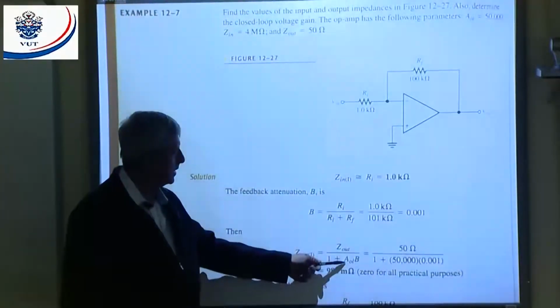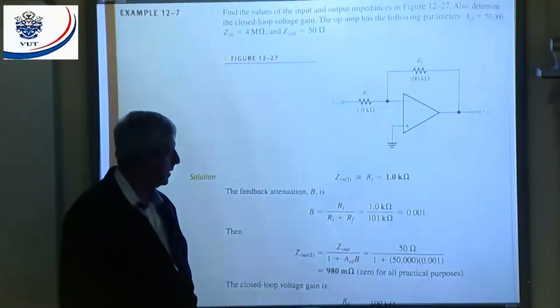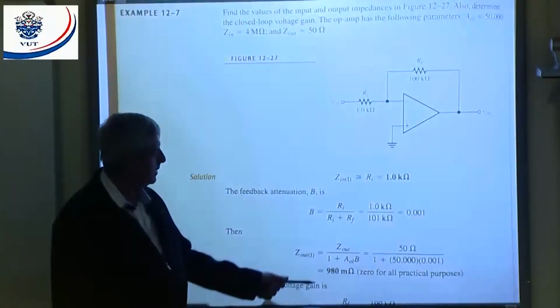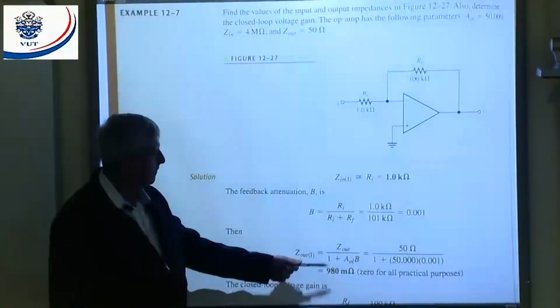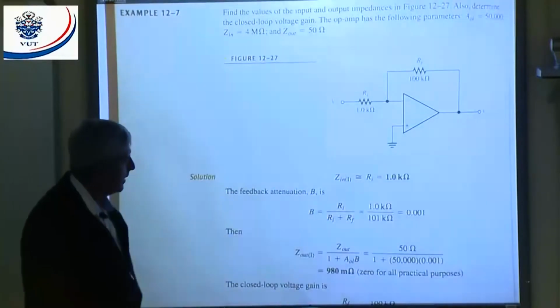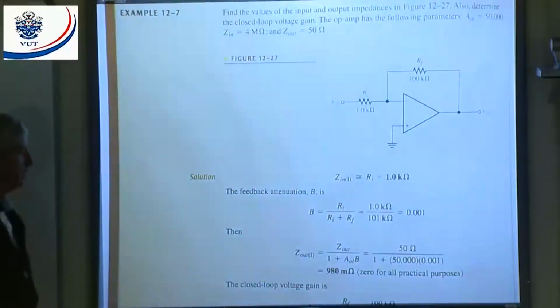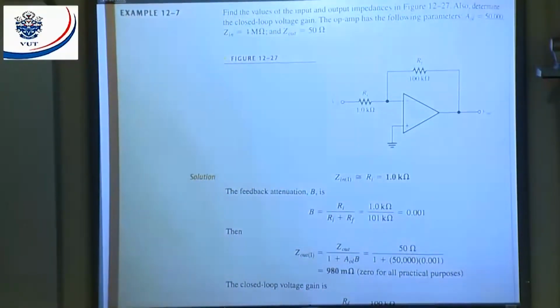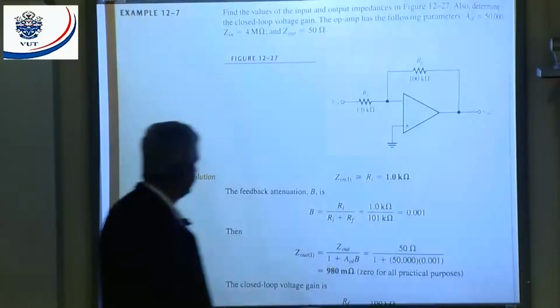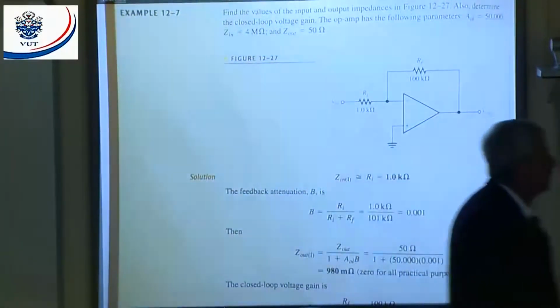And a closed loop gain, we're going to look at 100 kilo ohm and 1 kilo ohm. It will give me a gain of 100. All right. Minus sign, I repeat again, minus sign indicates 180 degrees phase shift between my input and my output. All right. Because that's the inverting amplifier, I will have 180 degrees phase shift. Any questions? No questions. All right.